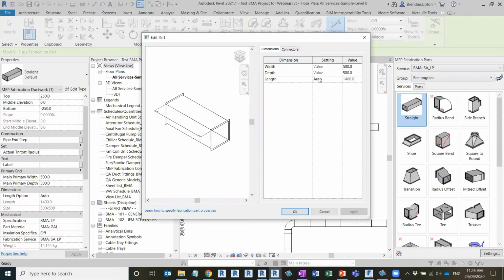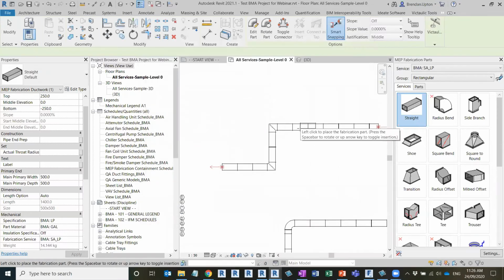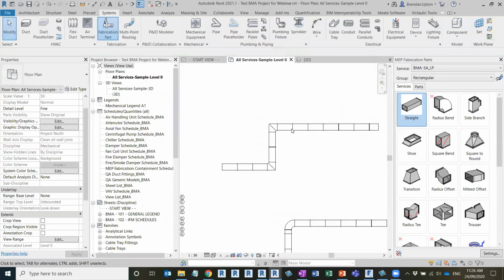In Revit, there are some limited ways that you can edit this stuff. So it is, to a certain extent, editable, but there are some workflows to be aware of, and sometimes it can depend on how the database is set up, because some of this stuff can be locked out. So don't just assume that you can put whatever length you want. There are certain factors involved that you have to be aware of, but effectively the option can be there to change that length out. All right, so that's the design to fabrication conversion.